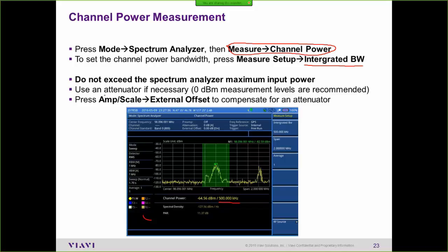Okay, well, if you need to convert from a trace level to a channel power level, then you can use this formula if you want to do that. Essentially, it just scales it up. So if I had 10 bins that I was trying to get the power level for, I could use the channel power measurement and have it do it for me, or I could do it this way with the formula, either way.